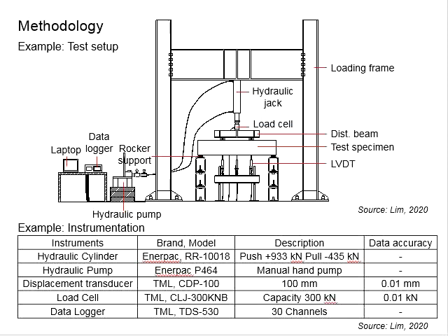And then you can have a camera to snapshot the crack patterns on the surface of the beam. You can only see the surface of the beam. How do you know what's happening inside the beam? Any movement between the polystyrene and the concrete? What's happening to the reinforcement bar? Even the crack, you only see on the surface. Is there any cracking within the member? Or how deep is the crack in the member?